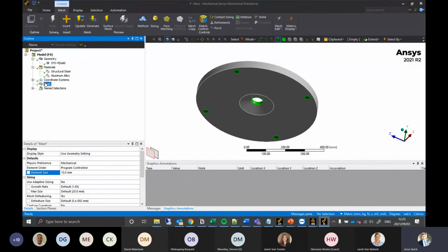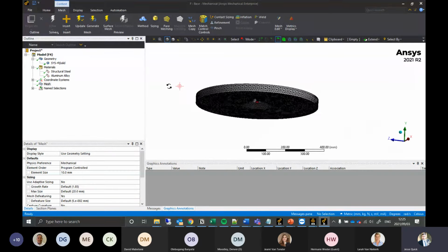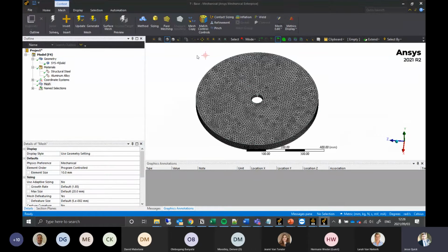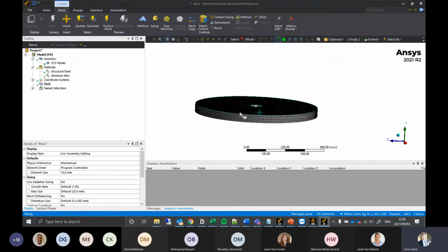So now we've got everything over here. We can mesh this very, very quickly. And here we've got all of our TET elements. So generally for the topology optimization, in this case, I didn't have to define anything. It defined it for us. But you actually do want to use TET elements for the topology optimization mesh. And the quality of the result that you get out of your topology optimization will be dependent on the mesh that you create. Okay, so we are done with that model.